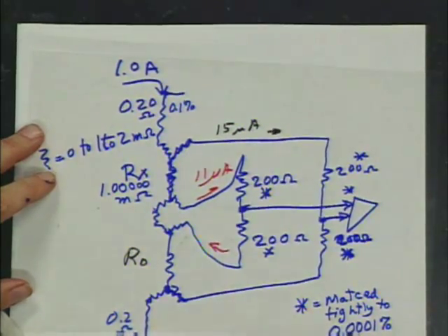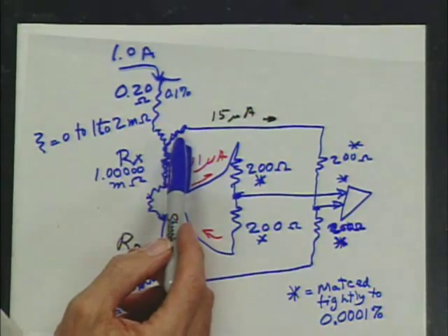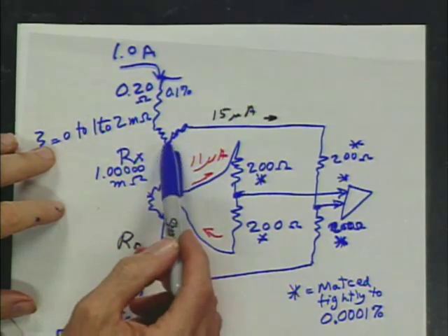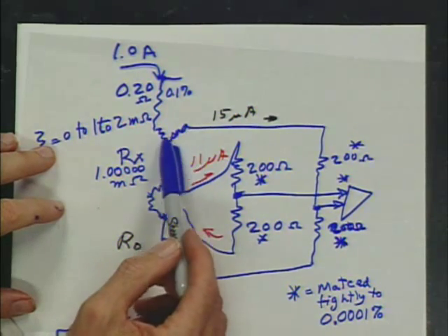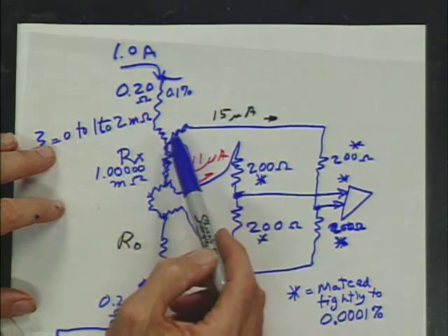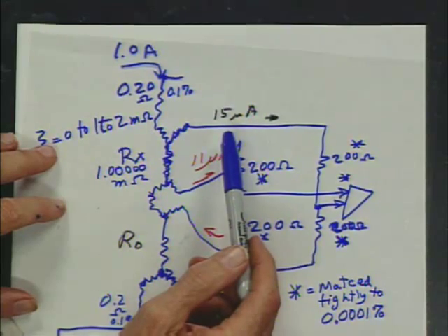Now, let's say we have an ampere flowing, DC or AC, through these resistor bridges. A milliohm here, a millivolt here. But this could be 15 microamperes times 3 nano-ohms, which is 45 nanovolts.